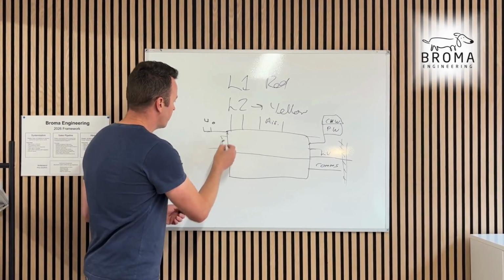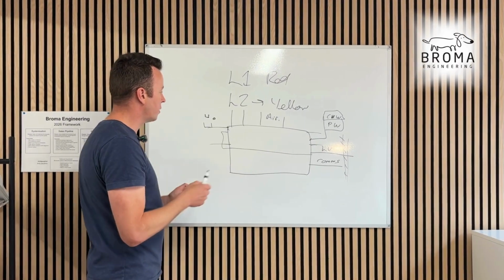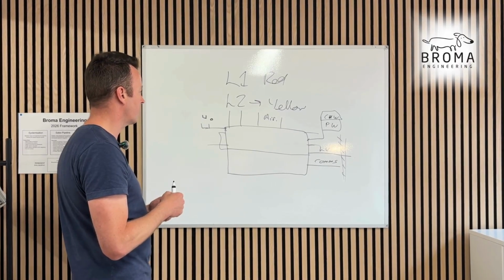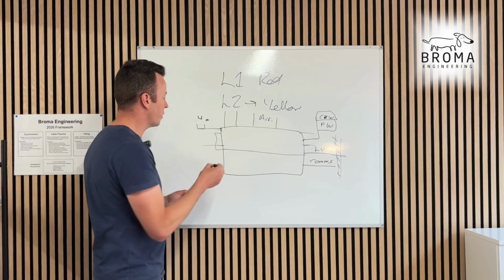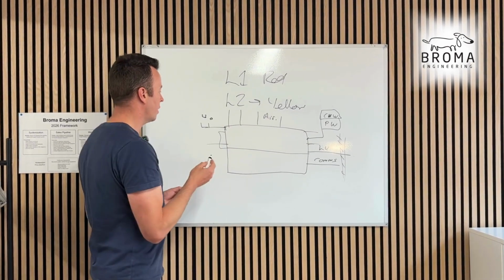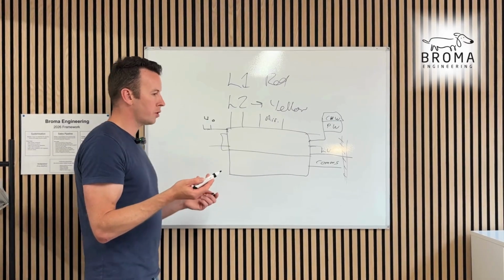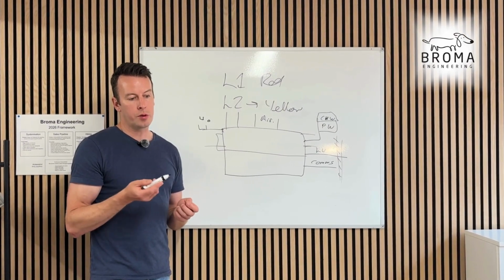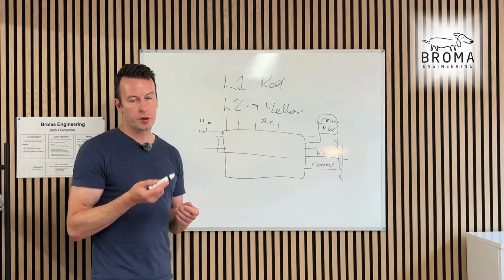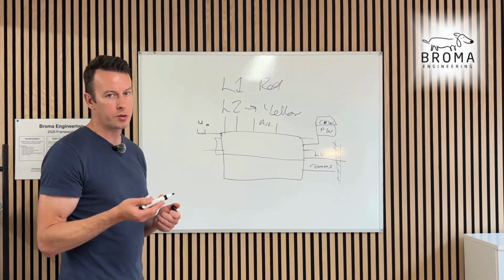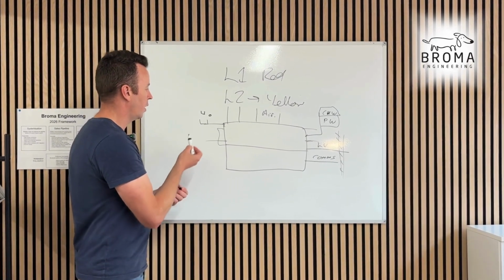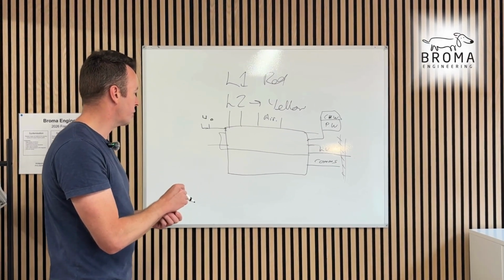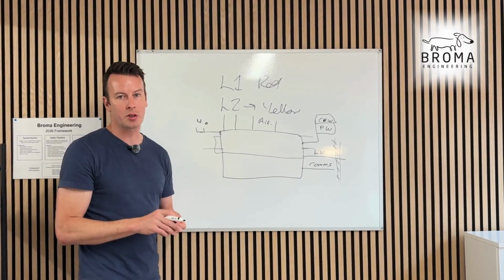You'll have BMS panels and comms cables coming in. Model it in detail. Get it signed off. Tell people, look, we have it modeled in detail. This is the way it's going in. This is the way it's coming down off the basket, off the cable tray. Same with the LV connection. Understand your torque settings, torque marking, what torque you're putting on the cables. We'll do a whole QA/QC on cabling. Make sure the cables are tested on time, that the test team know the scheduling, that testing is in the schedule, and they're ready as well for level 3. Anyway, you have to plan the inspections at the end.